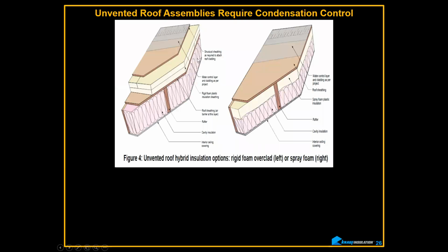Again, you can do this on the inside with an impermeable layer, like either closed cell foam or rigid board, anything that's semi-impermeable or impermeable, or on the outside, but the outside, again, does not have to be an impermeable layer. It can be anything. It can be rock, it can be glass board, whatever it is, as long as you got the right R value to keep this sheeting as warm as you can.